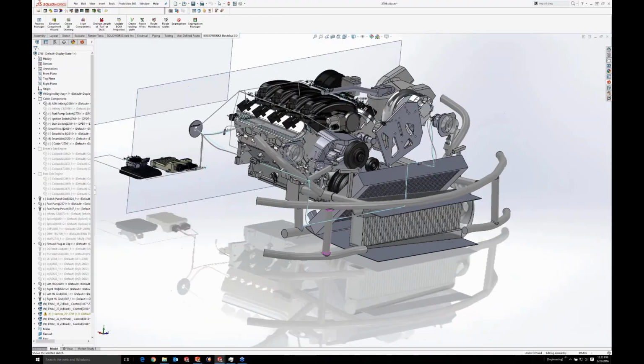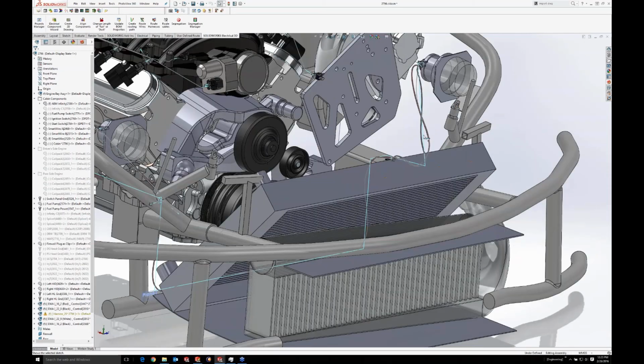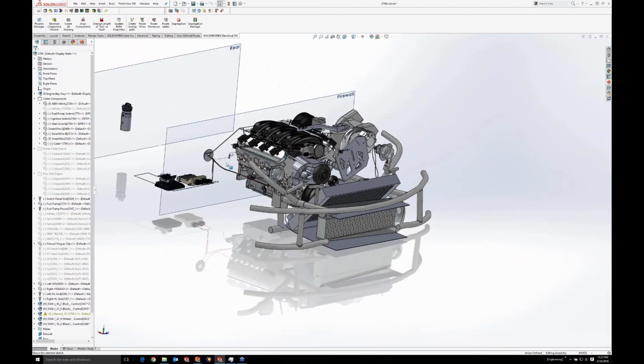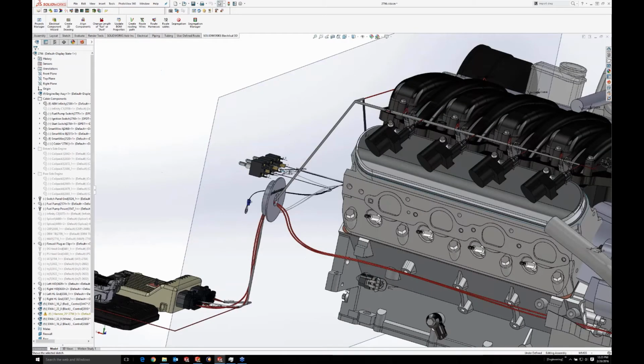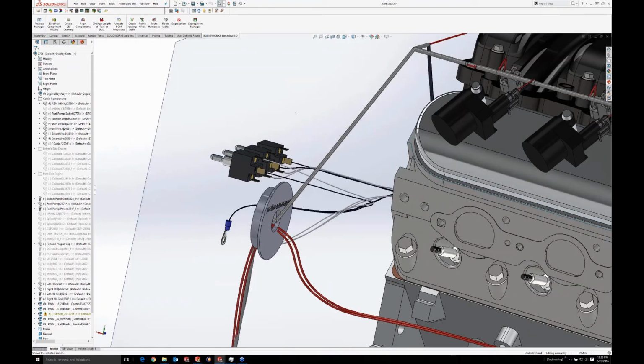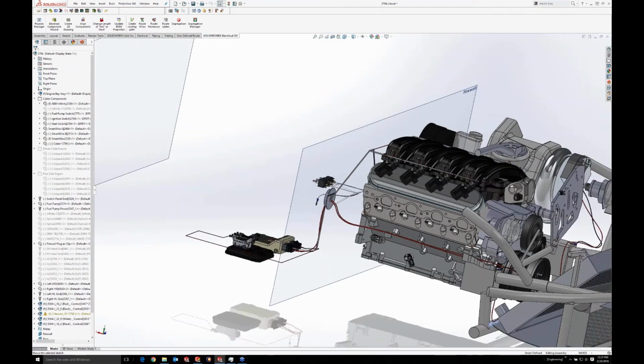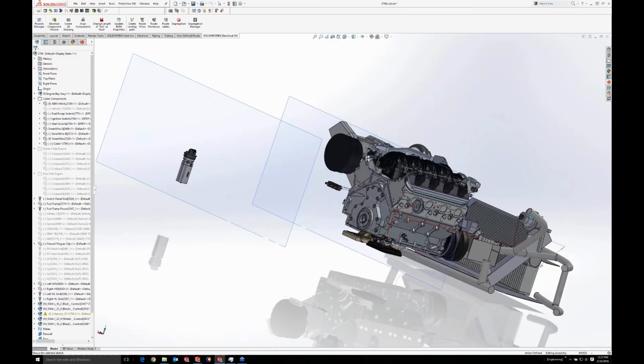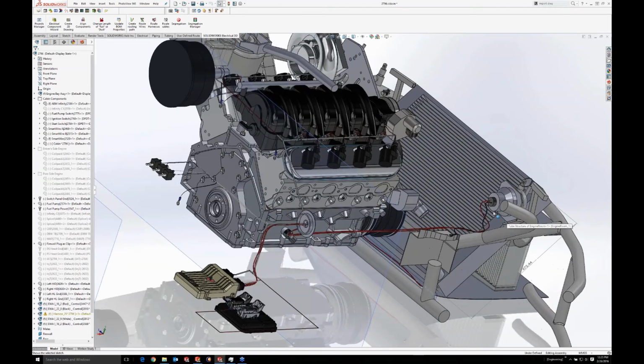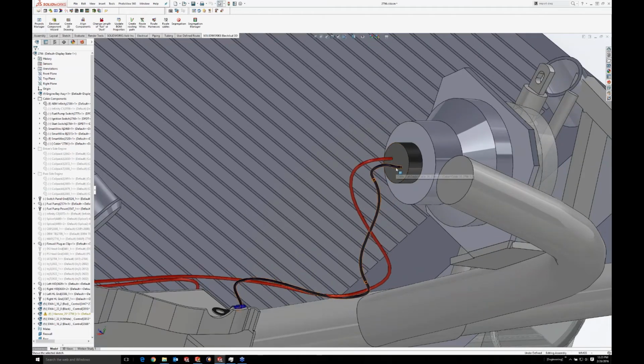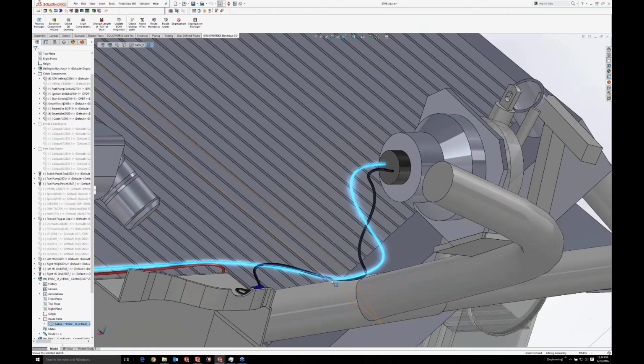We also have one, you can see this teal up here for my headlights. So I'm going to hide sketches so that the sketches go away and you just see the wires. Similarly to, let's turn off my route points, a little too much text in here. So similarly to these white and black wires for these switches, I ran some thicker wires for my headlights. So these are a couple of headlights hanging out here in space. You can see they've got a red and a black wire, beautiful splines here. I didn't route those manually.